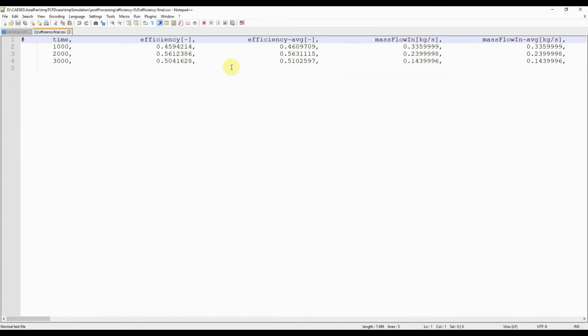For example, we need to take the average efficiency, of course, and we can take the average efficiency of each simulated point. This file we will put into CAESES to be able to get the results from each simulation for every design variant and so on. So at least these two files we need to have for creating the connection.